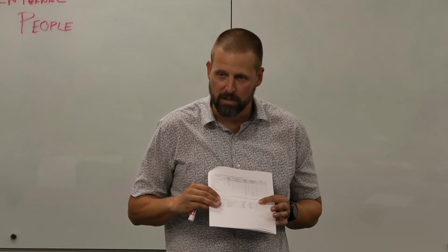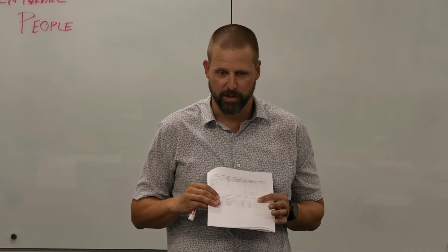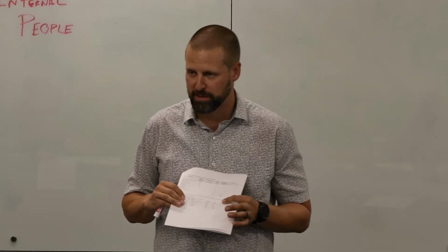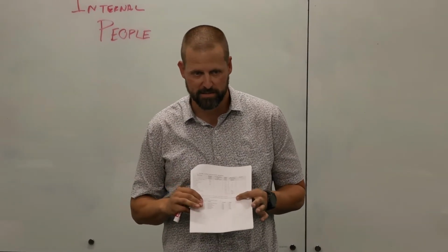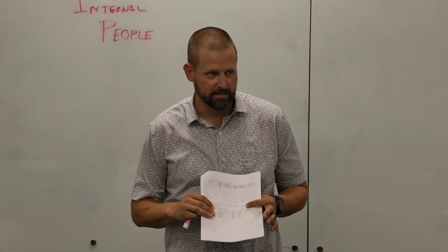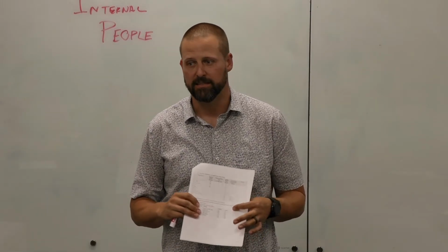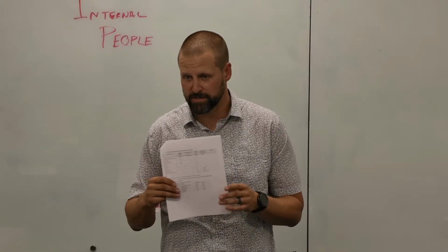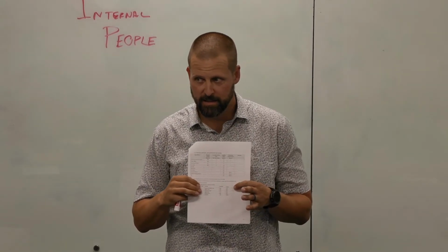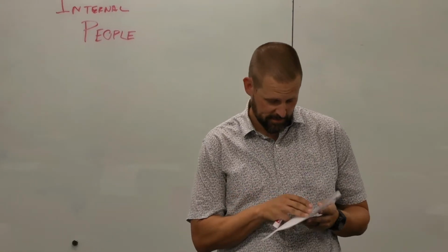If you are in a gym on a treadmill, you're pumping out a lot more BTUs and a lot more sweat, latent load, than if you're in an office sitting. The one we use the most in this table, any guesses? Stationary work. Number two would be good.